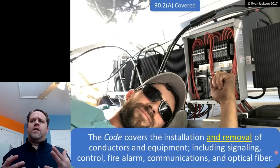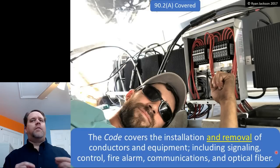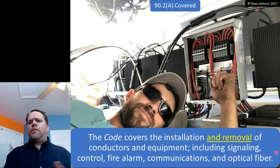of those circuits and I discontinue it, so I cut it at both ends, I stop using it, or I just undo it or turn it off, the code requires that I remove abandoned electrical cables, low voltage cables, communications, again, fire alarm, things like that. And it's not necessarily that the cables are unsafe. I mean, they're not being used. So if they were safe while they're being used, while they're energized, how are they suddenly unsafe when I remove the voltage from them? Well, they're not unsafe in and of themselves, but here's the problem.